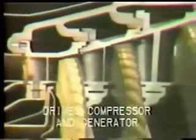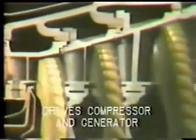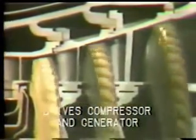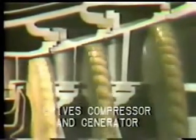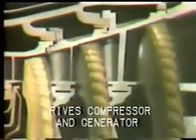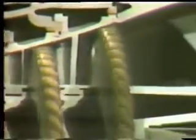These hot gases expand through the turbine section, deflect the turbine rotor blades, and turn the turbine rotor. The turbine rotor then produces the power to turn the compressor and produces the power to turn the electrical generator. As the expanding gases flow through the turbine section, their temperature and pressure drops, and they ultimately exit the turbine into the atmosphere through the exhaust diffuser.